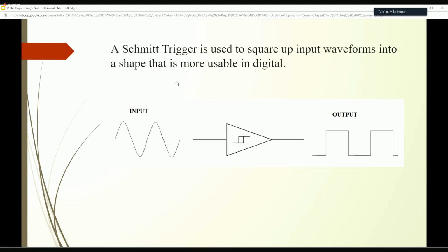If we go back to some of the original slides that we looked at, we had a signal that looked like this square wave, right? It was very vertical when it went from a low to a high and back down to a low. We got these sharp edges, and what that allowed us to do is use that square wave to time and trigger these latches and make sure that they were sequenced right.